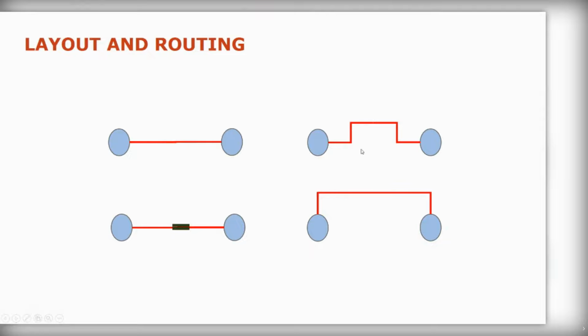There still will be loads, but they'll be quite low, and you can direct those loads by cleverly putting your supports. What would be a mistake is to put a massive anchor on those corners, which I don't think anyone would do, but if you were, you're defying the whole idea of what we're trying to achieve here. But if you have anchors around here that allow the pipe to slide upwards and forwards, then that whole thing will work quite well.